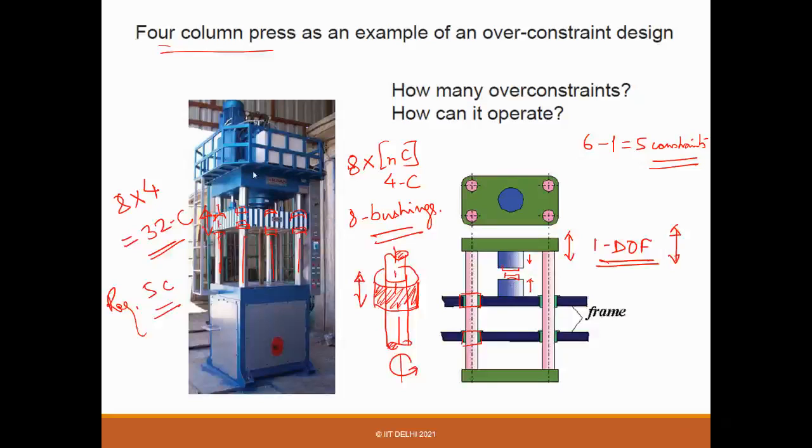Perfectly parallel, you say, okay, I can make it up to 4 micron, 2 micron, 1 micron, whether you can go to the nano level, right? Going to a very precise level means a lot of cost. You need a lot of tooling. And obviously, no matter what you do, you cannot go beyond a certain extent. Maybe of the order of a micron you can achieve with very good use of tooling, right?